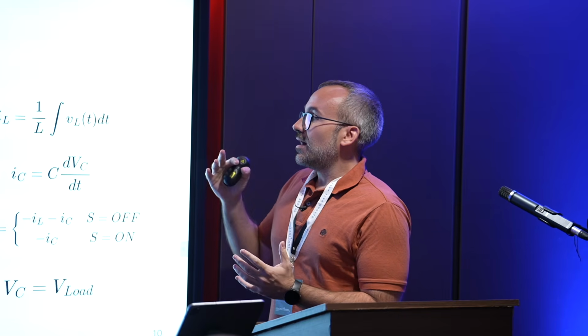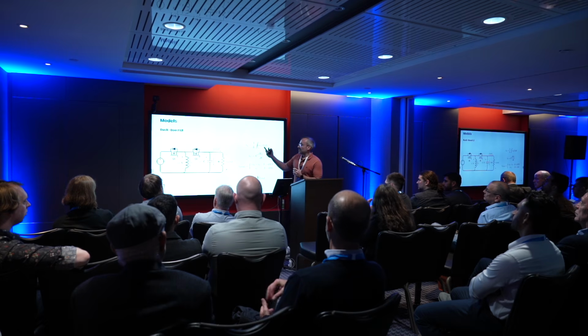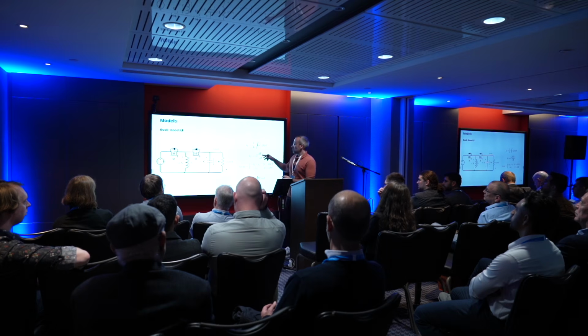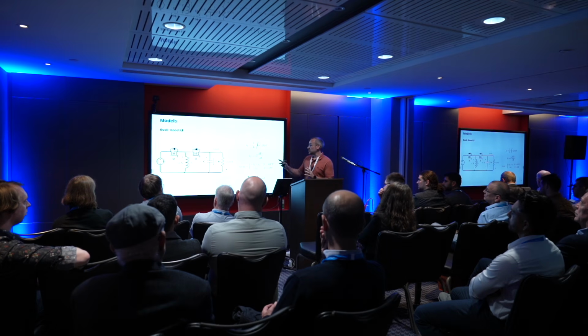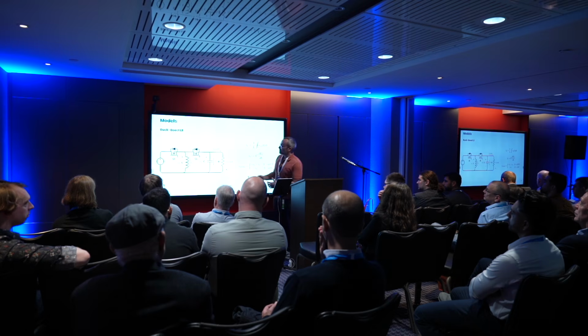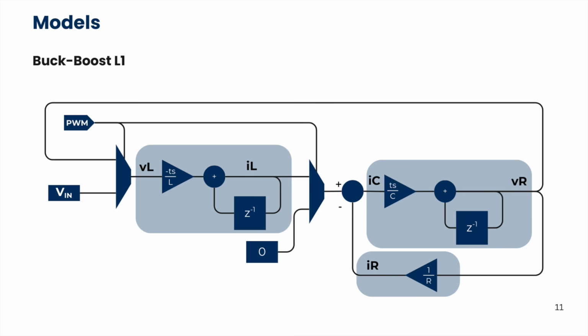So if we want to implement this into the FPGA, we are going to need to translate all these equations into some synthesizable code. And it is very easy because I know that FPGAs cannot do integrals, or they cannot do derivatives. But an integral is essentially an addition, a derivative is essentially a subtraction, and this is a multiplexer. So we can translate this diagram into this diagram. Here you can see these two multiplexers that represent the nonlinear equations of the two switches.